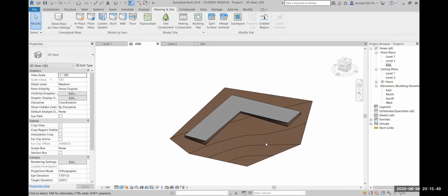What if we have an AutoCAD site plan readily drafted, can we import it to Revit and do the same, ma'am? Yeah, that's what I said. If you have an AutoCAD plan for any slope site, that's what you have to import, and then you have to create a site using the AutoCAD plan. We have to import the contours and then create the site, right? Yes, because the site plan which you will have will have the contour lines also. You have to import the contour line file, and then create it by selecting this option.